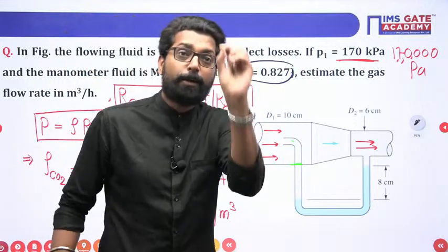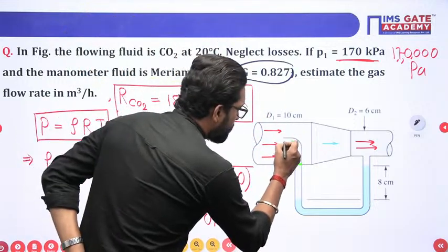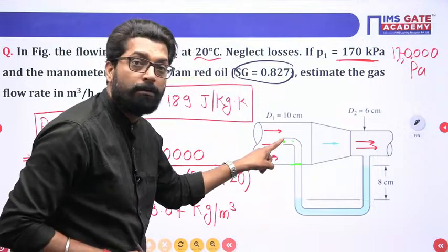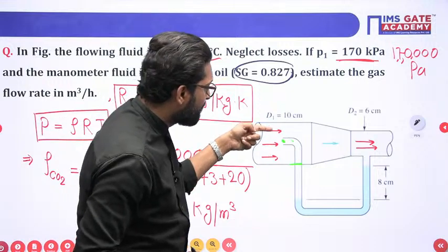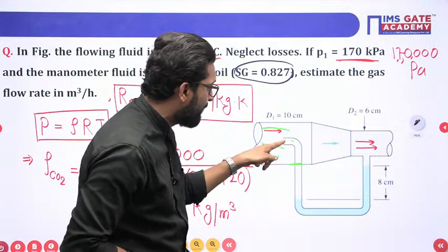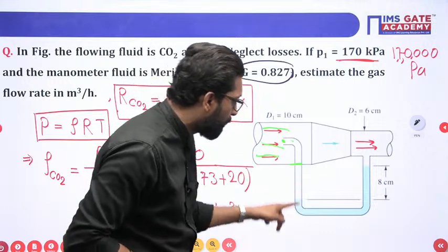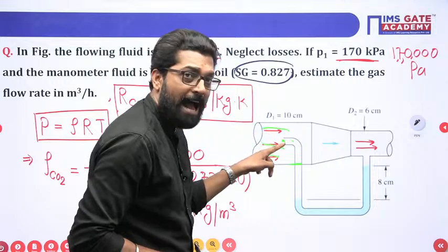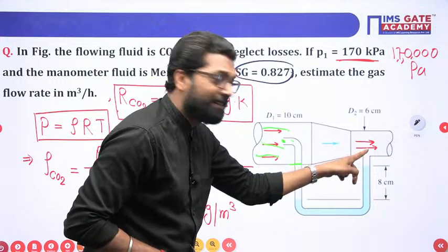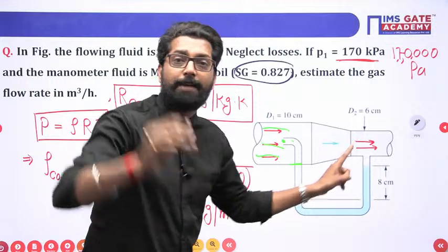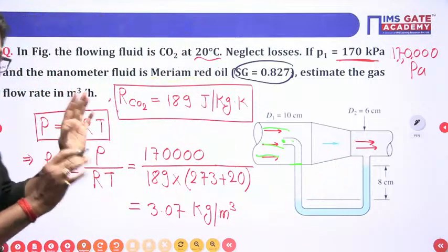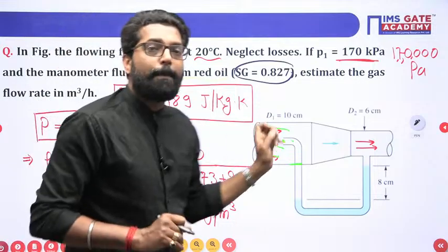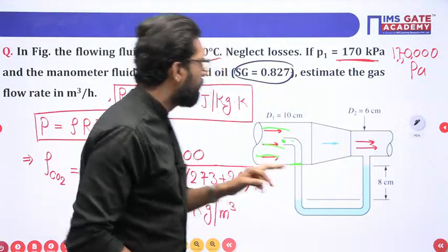And the characteristic of the Pitot tube is that the velocity at this point is 0. Once you apply the Bernoulli equation, the velocity at this point is 0, pressure you have, but the velocity at the other point is there, so you can easily find the velocity. The first thing required is to apply the Bernoulli equation between these points. I will just tell you.